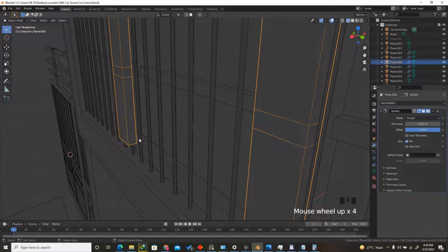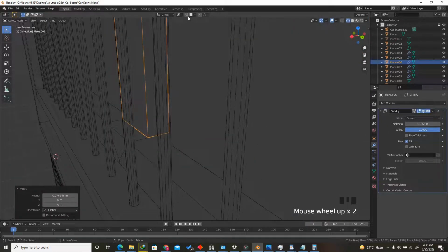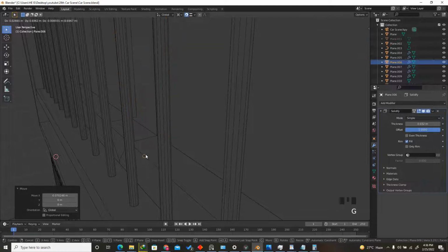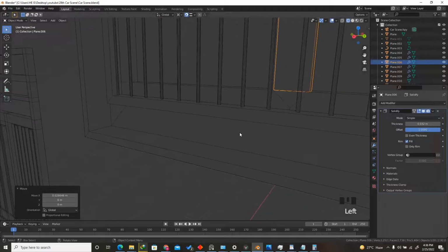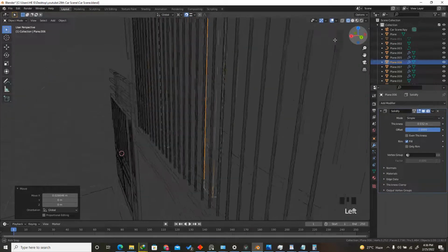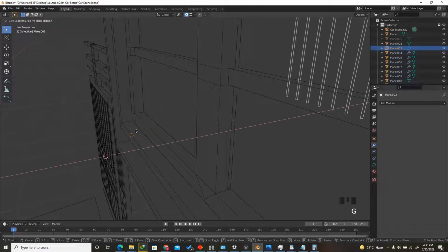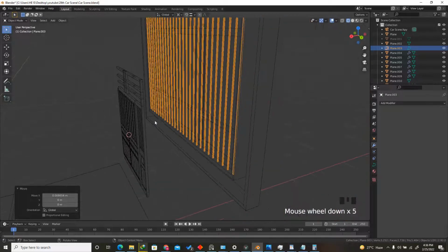Let me press GX and then move it a little bit backward. Let me activate this snap button, and let me change this one to edge selection mode, and then press GX and snap it to this edge like this. Yep, I think we have fixed the problem. Maybe select this one and then press GX. Let me deactivate the snap button. Press GX, maybe move it like this. I think this will be good.